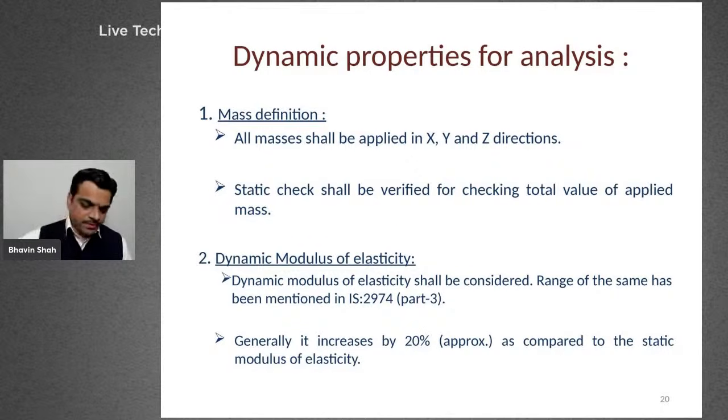So firstly, whenever we talk about the mass definition, then all masses shall be applied in x, y, and z directions. And always I put up a static check. Let's say after providing all masses in the foundation, then we consider a static check to verify whether the applied mass value is correct or not.